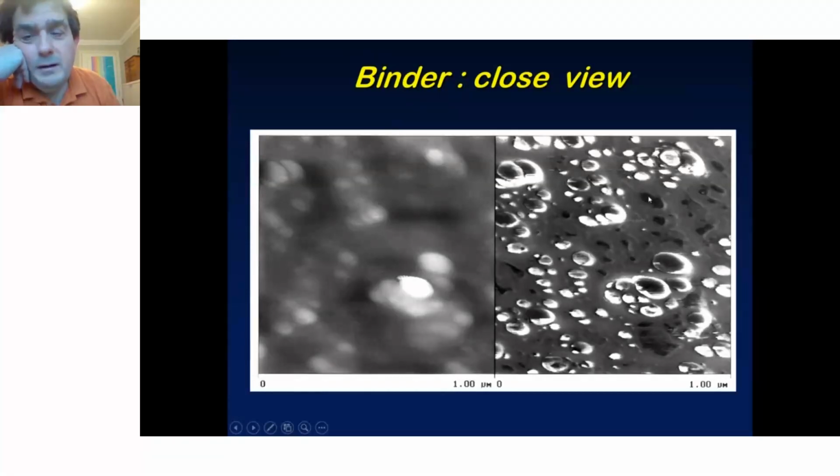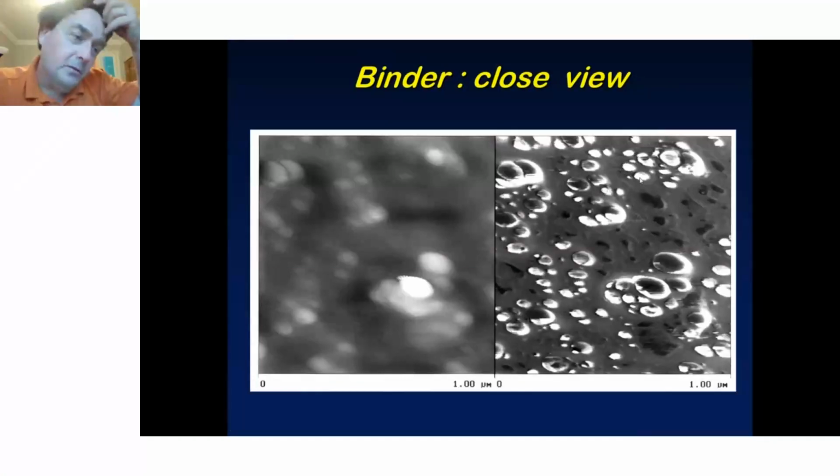So what we are in effect seeing here are very small amounts of small size explosive crystal grains caused by abrasion of the crystals during processing that have been included in the binder. And these areas here are softer material, either caused by incomplete reaction or due to the lack of stiffening effect due to the presence of these small amounts of explosive crystal.